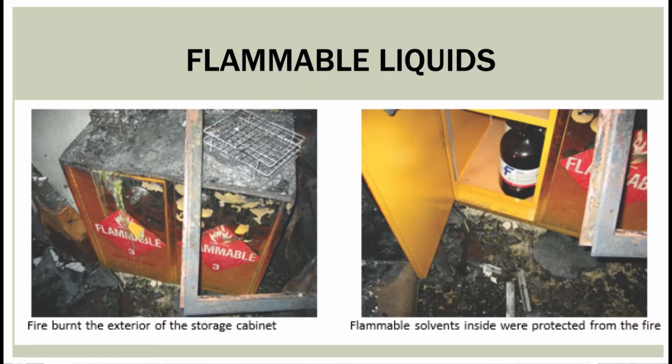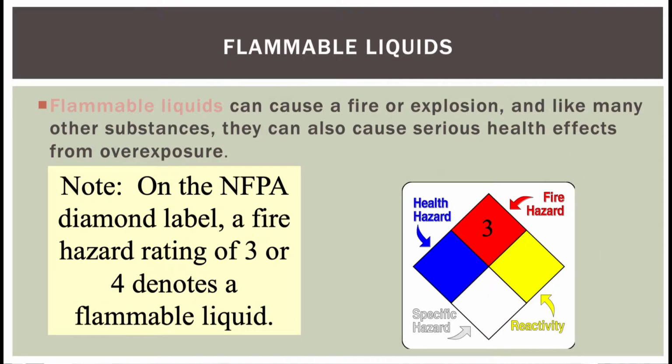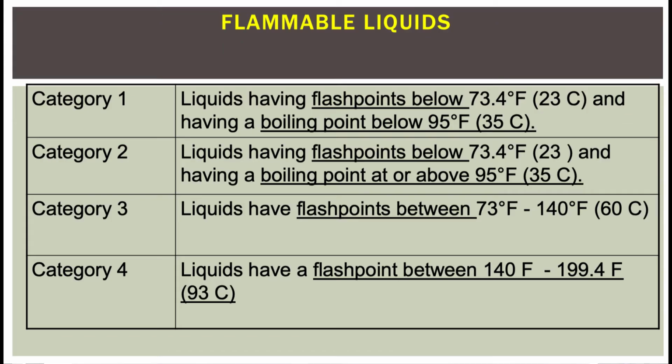So here, we're going back, we're leaving this area of talking about confined spaces and the lower explosive limit, and we're going back once again to flammable liquids. Flammable liquids can cause fire and explosion, and like many other substances, may have health effects. On the NFPA label or diamond, a rating of 3 or 4 means that the liquid is a flammable liquid.